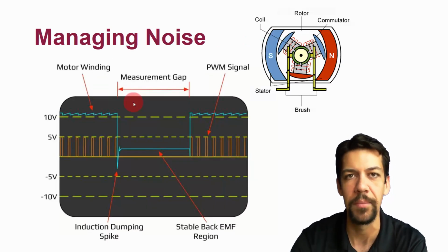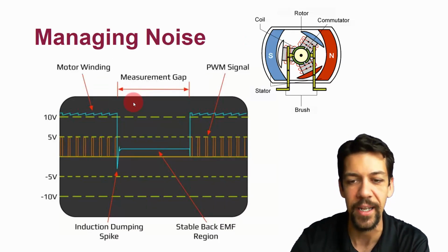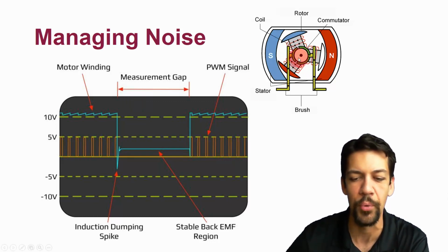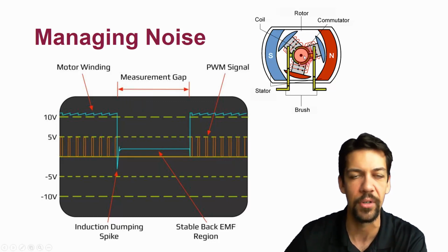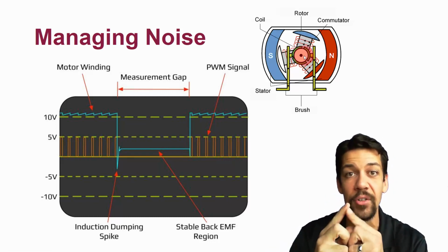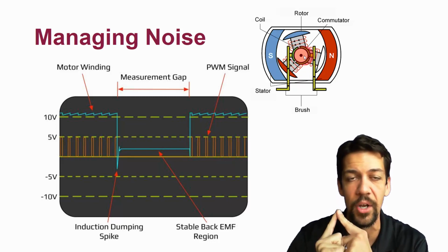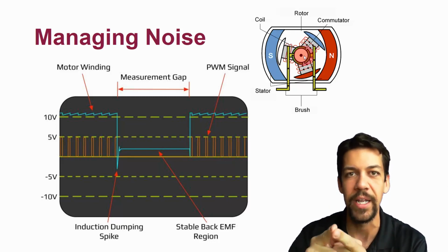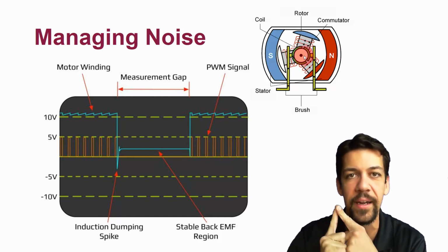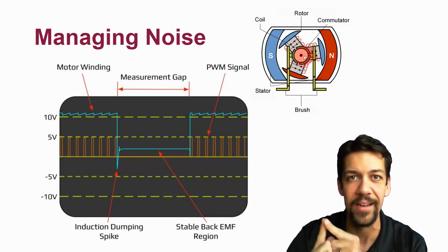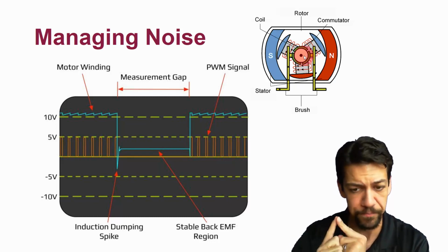We also have the problem that in brushed DC motors, as the commutator spins, we're breaking and making new electrical connections. That can often cause little sparks to occur, and those little sparks are radio emissions. Those are like little lightning strikes. If you ever heard the radio in a thunderstorm, you can hear lightning strikes because they are broadband electrical interference.